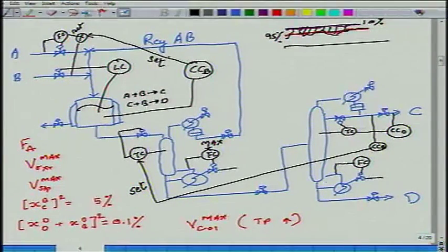Yeah, you can set this ratio set point at too much B, and then the ratio will get adjusted so that there is too much B in the recycle. You can set this composition set point at very little B, let us say only 5% B inside the reactor, and then the ratio will get appropriately adjusted, whether you are putting in extra A or extra B, that will get automatically adjusted. Yes or no?